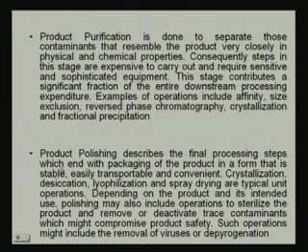The last step is polishing. Product polishing describes the final processing step which ends with the packaging of the product in a form that is stable, easily transportable and convenient. Crystallization, desiccation, lyophilization and spray drying are typical unit operations considered for this stage.